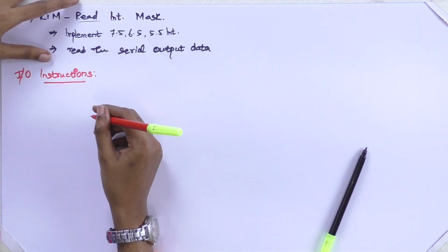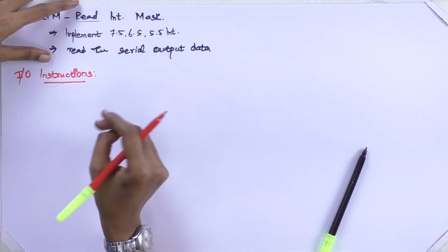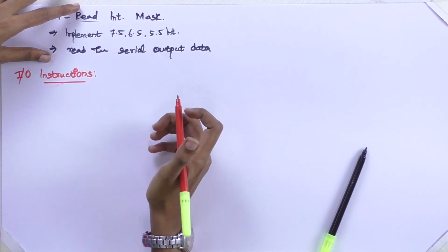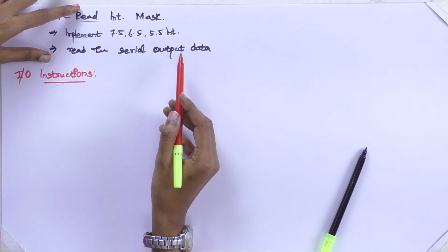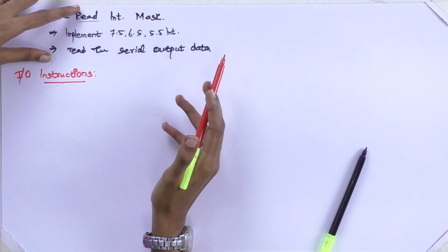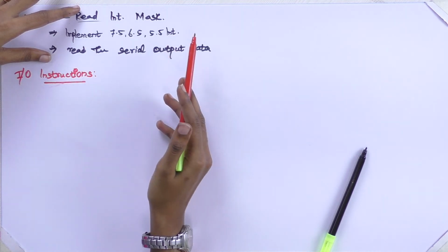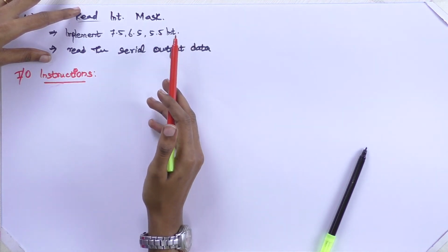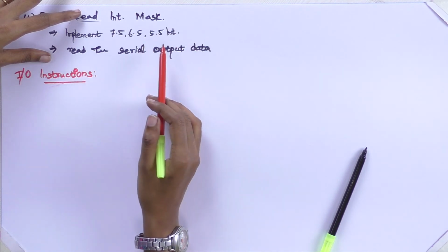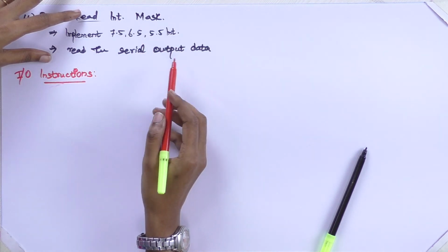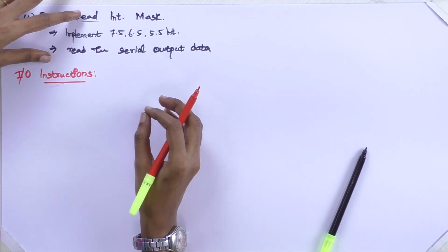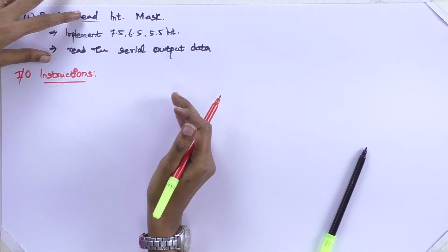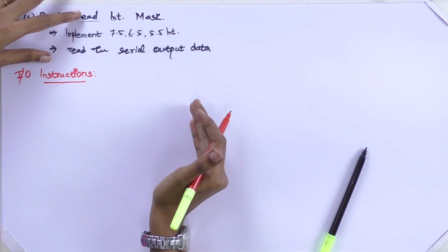So these input output instructions are used to read the data from the peripheral device, or to write or give the data to the peripheral device. As we have seen in the introduction class itself, peripheral devices might be your input devices or output devices, like your keyboard, monitor, mouse. These could be your input or output device for your processor in particular. Fine. So if you want to read a data from the input device, you are supposed to use the IN instruction. If you want to give a data to your output device like monitor, you are supposed to use the OUT instruction.